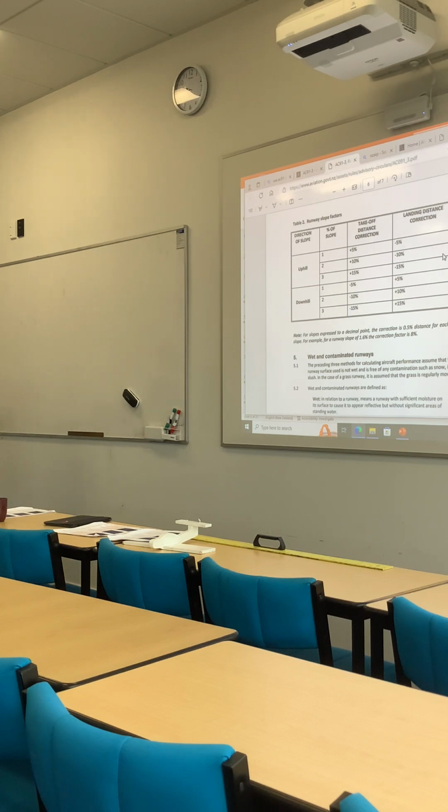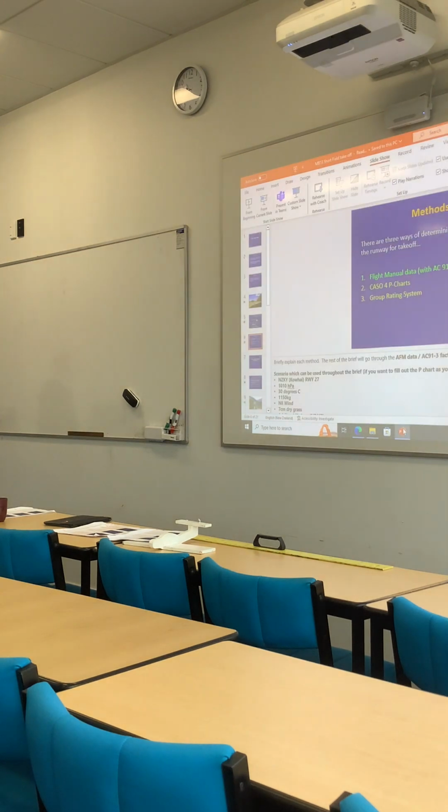Sometimes a manufacturer has specified correction factors of their own, and in the DA40's case, Diamond has. If the manufacturer has specified factors, you use the manufacturer's ones. You only use the AC 91.3 ones if there are none specified by the manufacturer. Okay, so familiarise yourself with AC 91.3 in your own time. Really important document for you to have a working knowledge of.